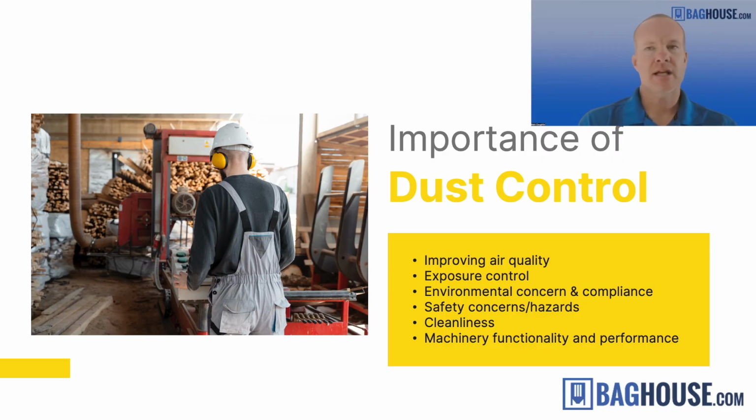Depending on the size of the shop, if it's anything bigger than a garage hobby shop, you also have some regulatory requirements. So you have your OSHA requirements, and then you have NFPA, which defines all the requirements for combustible dust. If you have a wood shop, it's pretty well guaranteed that you fall under the NFPA 660 and 664 requirements for combustible dusts, because wood is combustible dust.